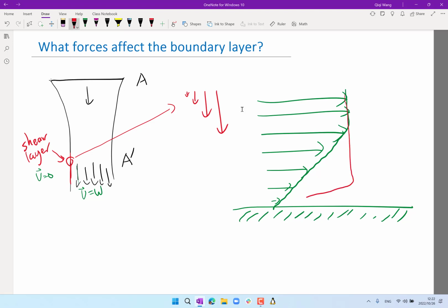Like that, thinner, right? Which boundary layer has more momentum? The red one actually has more momentum, because the velocity is faster almost at every y location. So if the viscous force depletes momentum from the boundary layer, it is going to change from the red one to the green one over time. The boundary layer grows thicker as the viscous force works against the flow.